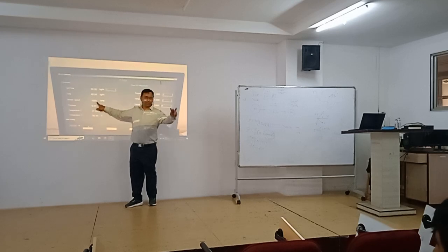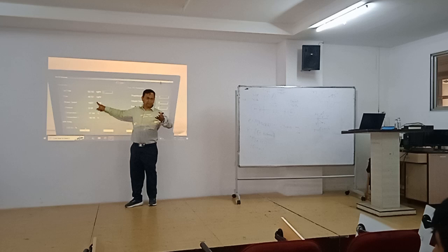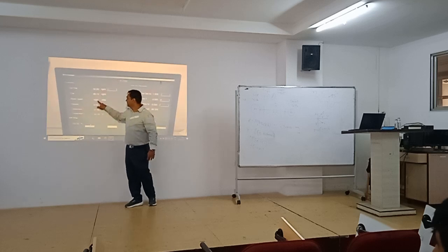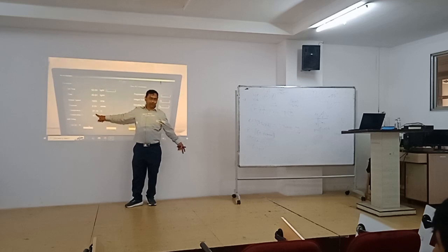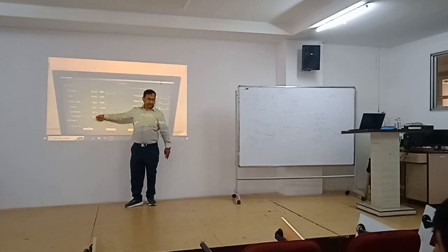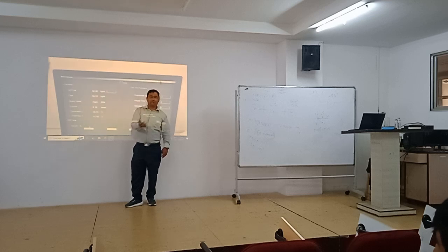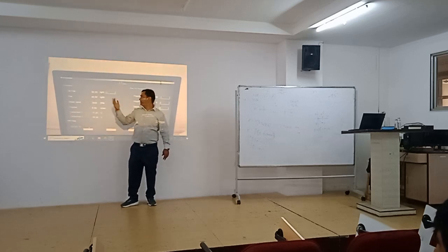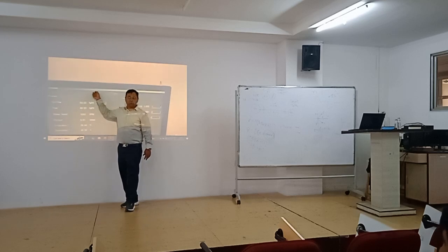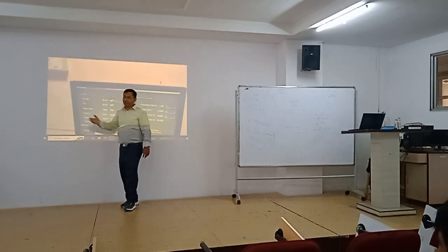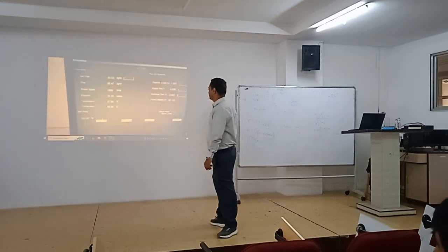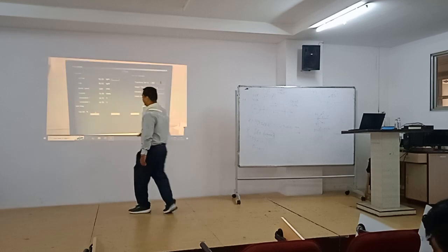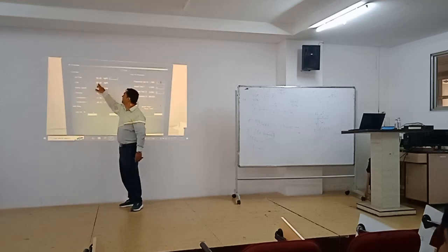See, earlier it was how much? 1867. Now it's becoming 1900. Why? Because see, the temperature has become 42 degrees. It was 30 degrees, now it's 42 degrees. So this temperature is varying. Because of that, mass flow rate would decrease, but the control system won't allow it to decrease. That's why it will increase its speed. So speed is increasing in such a way that the flow will be maintained.